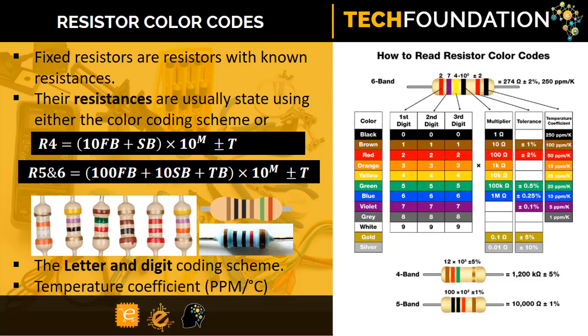Now a quick trick is this: any resistor with a black third band is below 100 ohm. Every resistor with a brown third band is below 1K or 1000 ohms. You can do the rest for yourself.